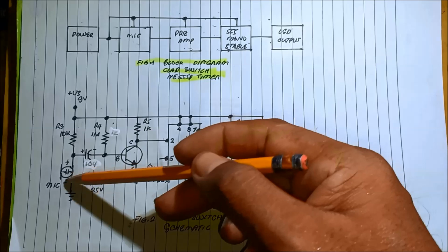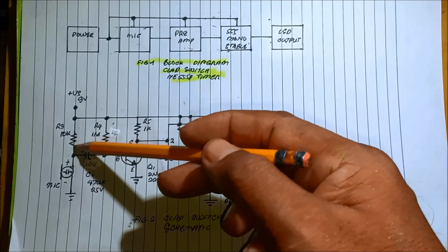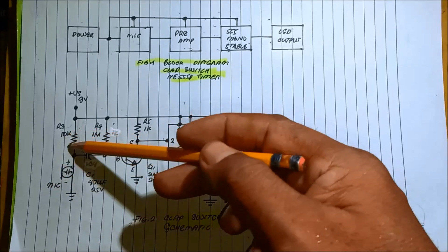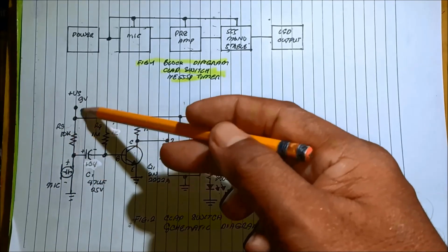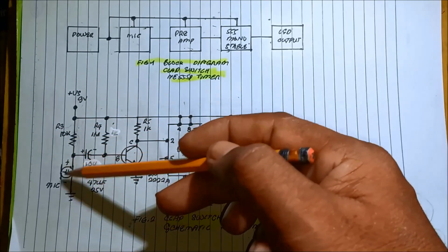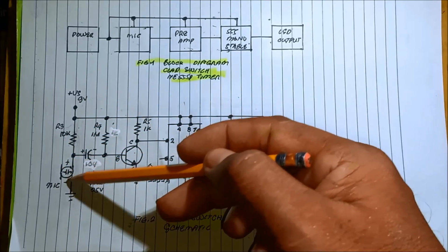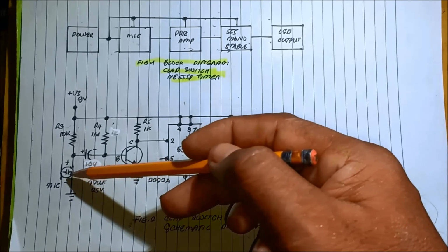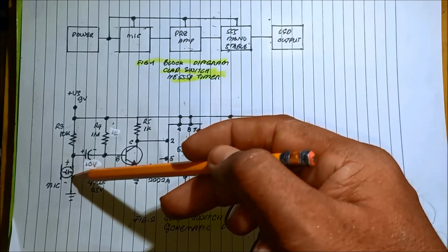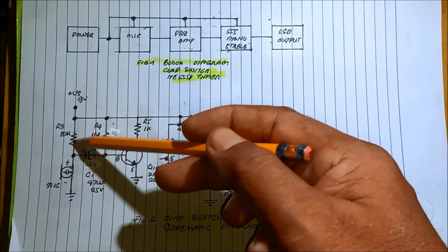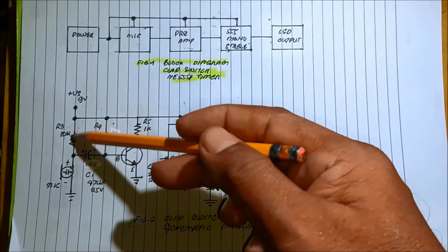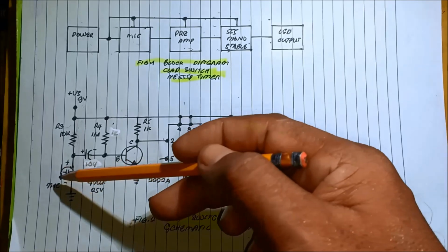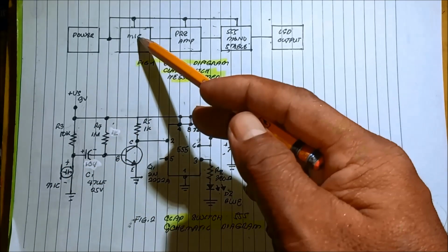To connect power to the microphone, we need a 10K resistor, so that this microphone circuit, 10K, is connected to the 9 volts, so as to power this microphone, because this type of microphone is a condenser type. We need the power of 9 volts. The current flows into the 10K and into the mic, that will power on this mic. So that is the first block.